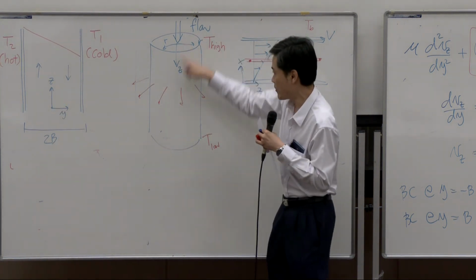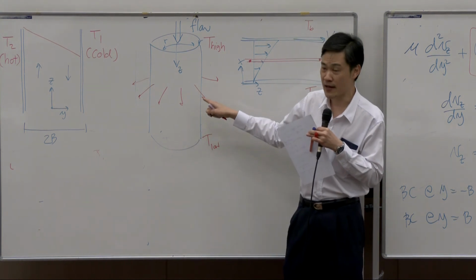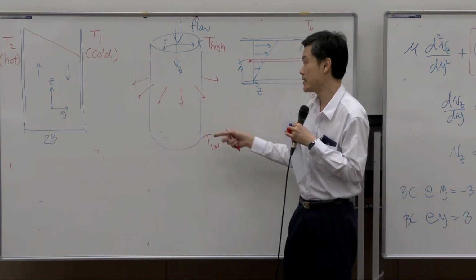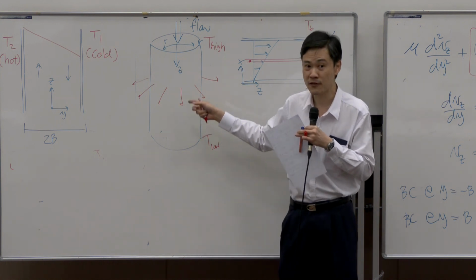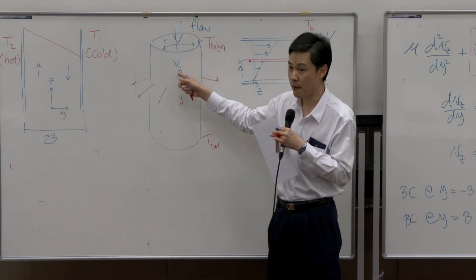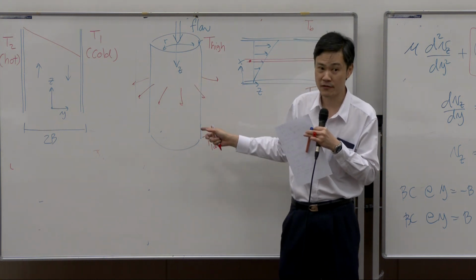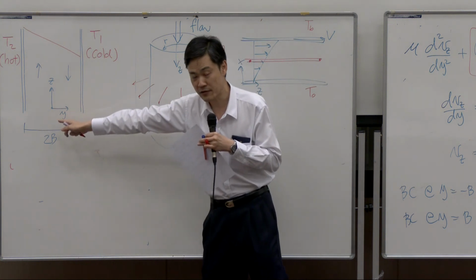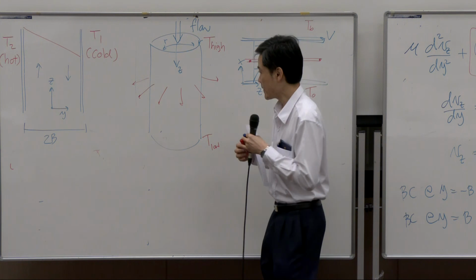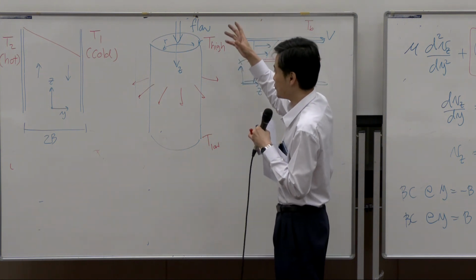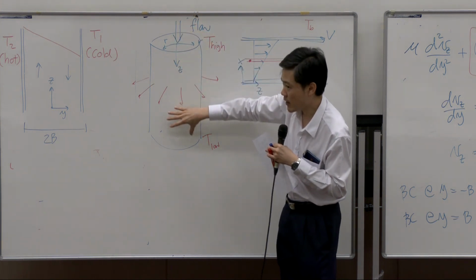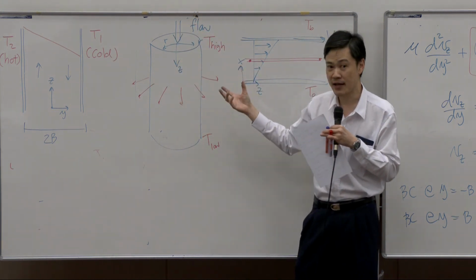So this problem, or these examples, would be the first one where convective transport is dominating. This is called forced convection. We force the flow, and the flow causes convection. This is natural convection. This is forced convection. The point that I want you to see is that, of course, this one has momentum transport as well as energy transport.